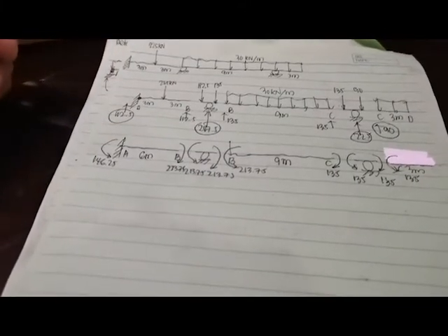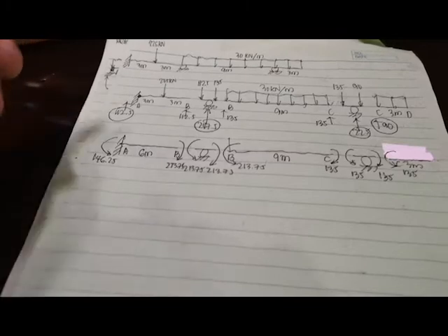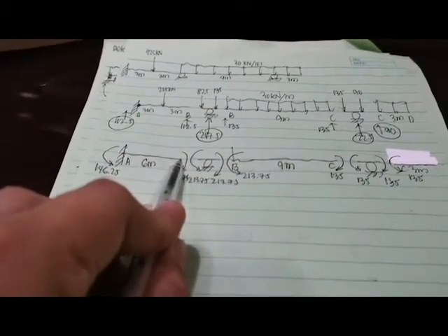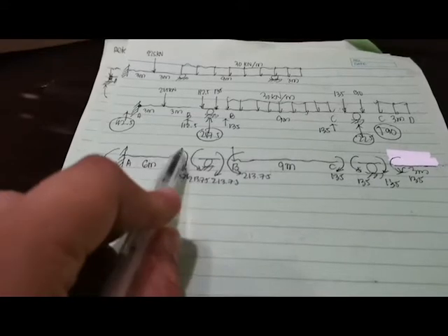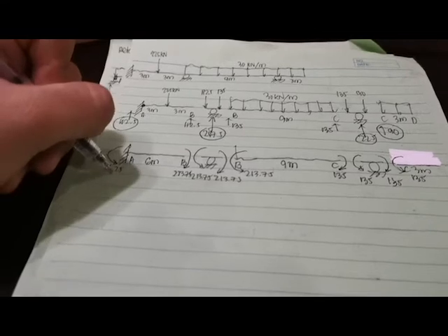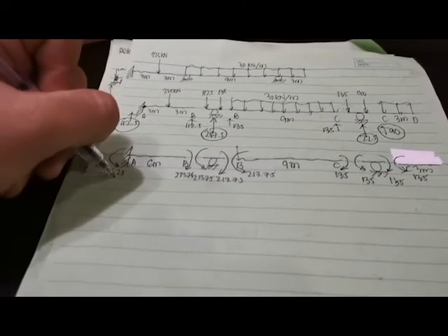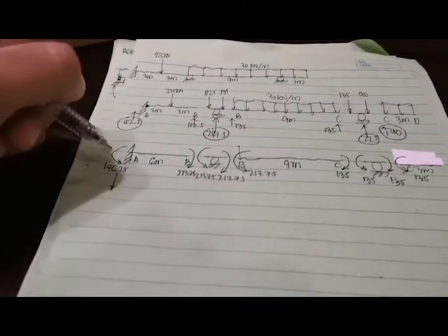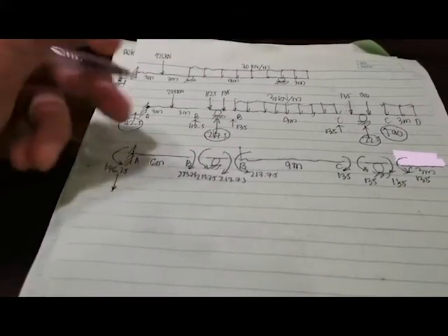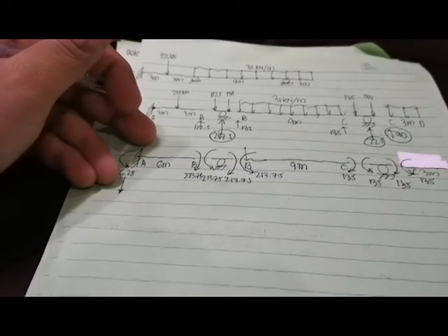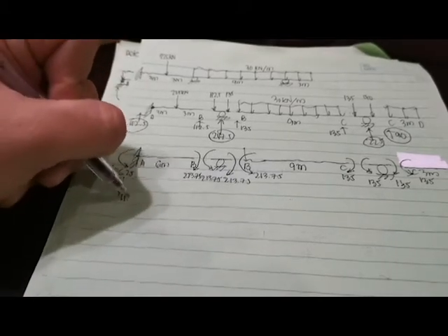So therefore, kapag nag-moment tayo at B, if we do summation of moment at B, and meron tayong clockwise na 67.5, now we can say na ang reaction at A natin will be equal to, will be downward, so 67.5 divided by 6, this is equal to 11.25.